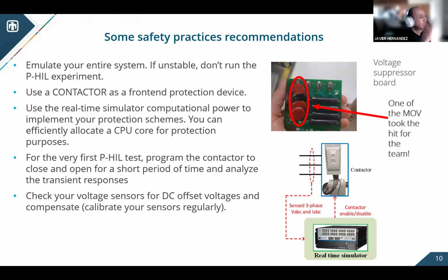All right, and then we just disconnect the contactor, and we check the transient right at the interconnection, and we check that we don't see any unstable behavior, and that sets the foundations for longer tests. Okay, but I think that this type of testing has saved us from really damaging the equipment, because we disconnect after 1 second when we make the first interconnection.